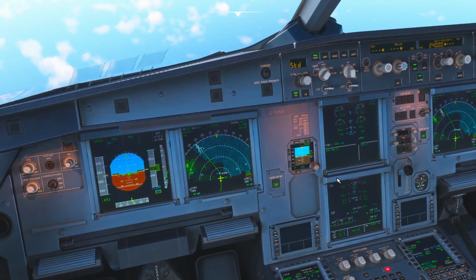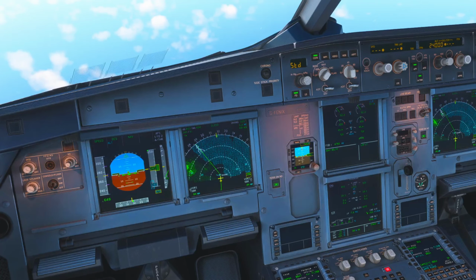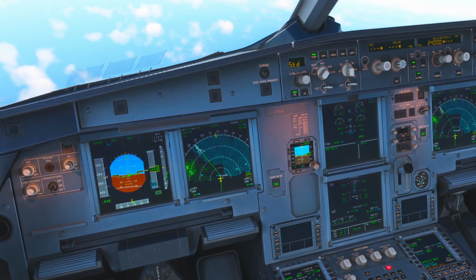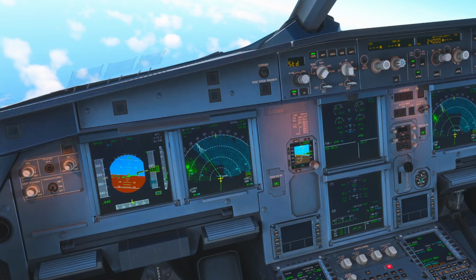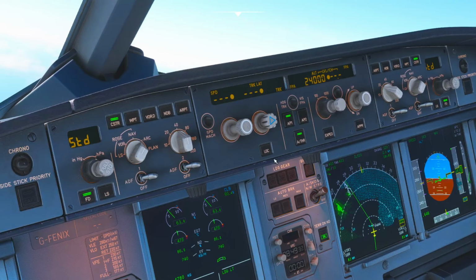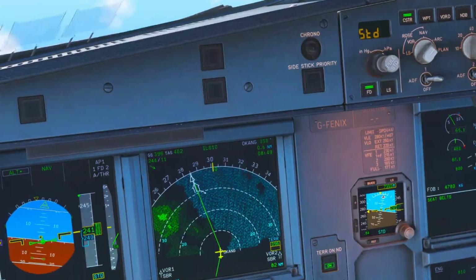For approach modes, there's the ILS localizer only. During the ILS approach, you may receive clearance to intercept the localizer of the runway, but are not yet given full approach clearance. This is when the localizer mode can be used. This mode requires you to have an ILS localizer. This button, the localizer button, will be shown in blue in the flight mode annunciator until the localizer moves off the full scale deflection towards the center.